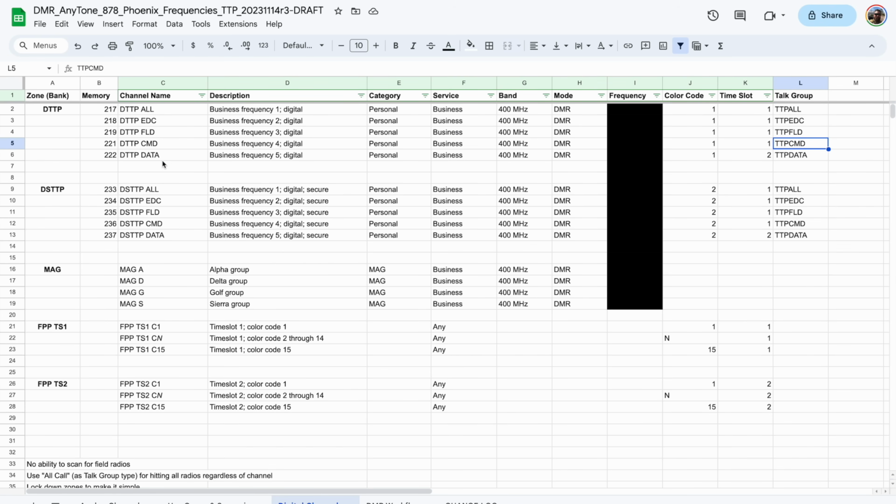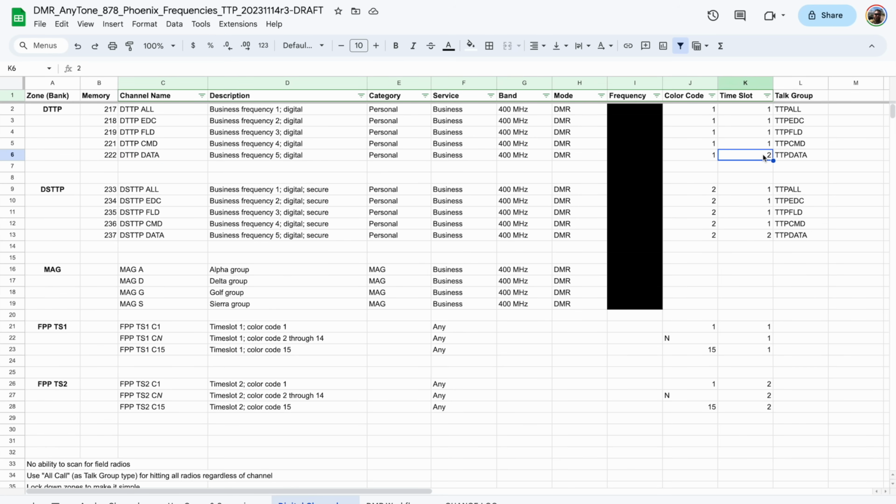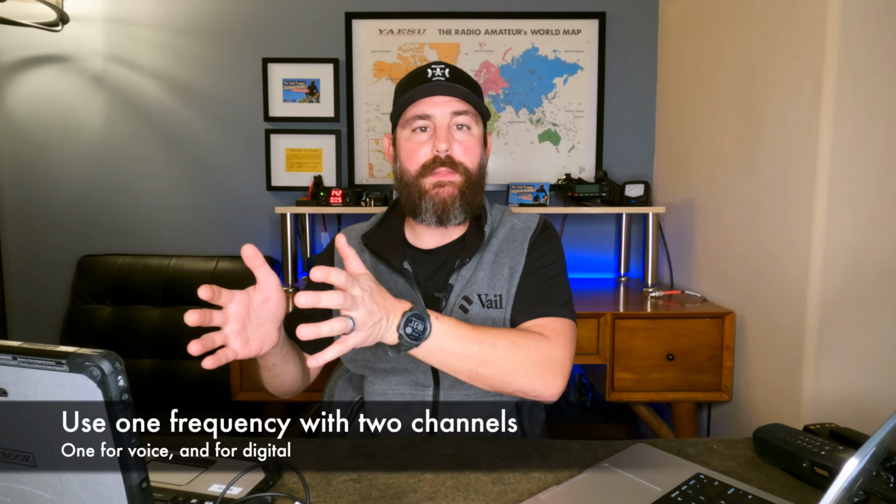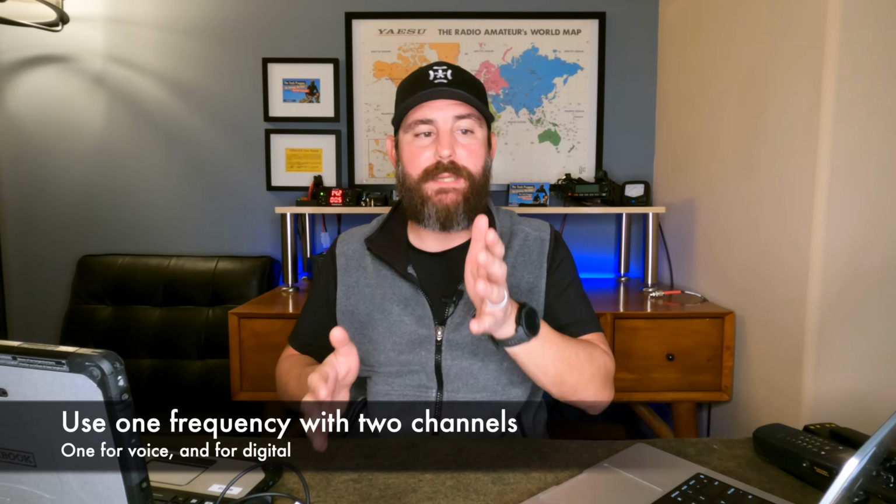The last one is for TTP data. This actually deals with some of the work I'm doing that you'll see in a future episode that deals with the Moto Turbo stuff that I have been working on. And I have purposely given it a different time slot of 2. The reason for that is that I can monitor basically voice and then digital on the other one by doing time slot 1, time slot 2.